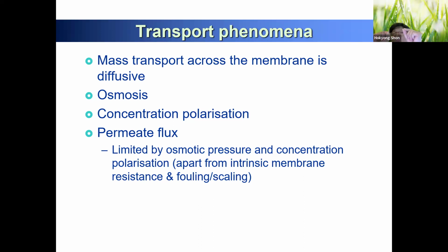If you know which membrane, which element, what the flux is, what surface you need, and how much each unit can produce, depending on your pressure, you can get your number. Then you decide we need to buy 1,000 elements, 2,000, 3,000, maybe 10,000 elements for the Sydney desalination plant, based on your scenario. So that's how you have to design.